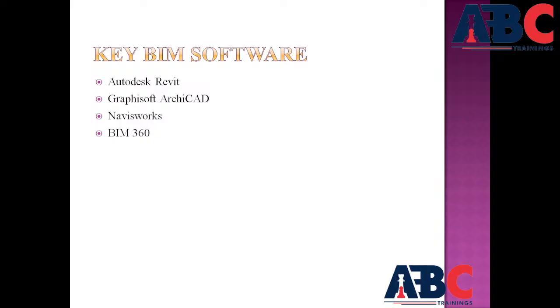Just like, suppose you are doing a model in different elements or different coordination manners, but in Navisworks you can combine all those three or four models in a single environment, and you can detect the clashes or the construction conflicts that happen in a model.